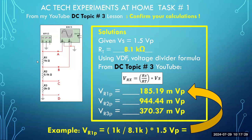We needed to find the voltage across each resistor because we said that a string of resistors, a sequence of series resistors is nicknamed a string, like a string of pearls, and I have a string of 3 resistors. We needed to find out how much of the 1.5 volt peak source, how much from the signal generator, is going to be divided across R1, divided across R2, divided across R3. It would be good for us to reiterate at this moment some principles behind series circuits.